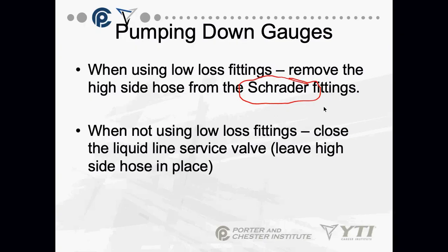Schrader fittings are the access points on the refrigeration system that look like tire valves. They have a little core in them that presses down and gives access to the system. Service valves are not used that often in air conditioning.